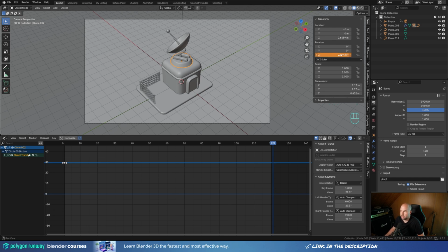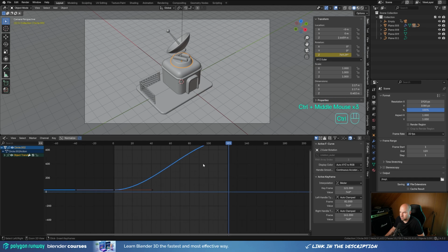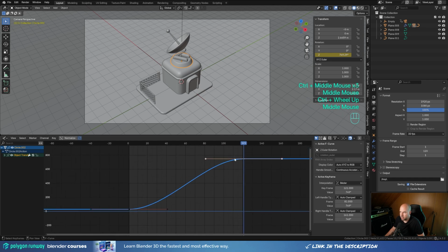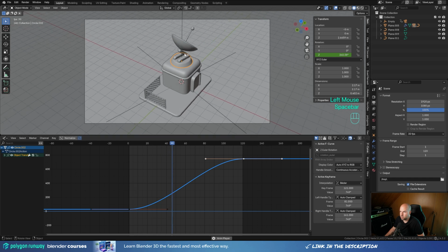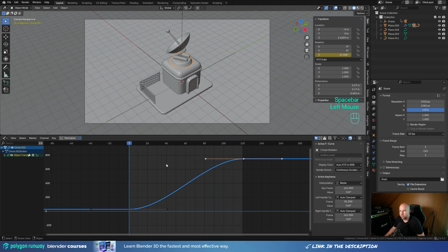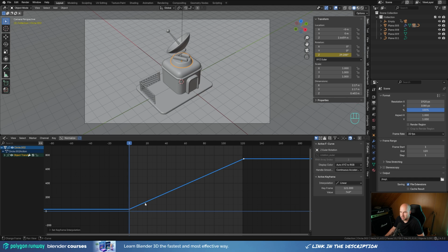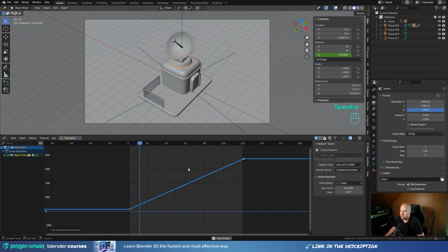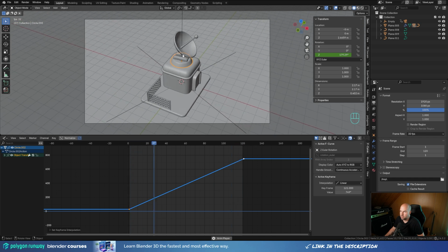It will do the calculation for us, so right click and insert single keyframe. And here you can see we need to kind of scale this down to see the whole animation, but this is easing, so anytime the animation starts, this would kind of go and then slow down. We want to move this linearly, so let's press A here to select all keyframes, press T and choose interpolation to linear, and you will see how the animation curve changes. So this will be basically still the same constant movement right there.